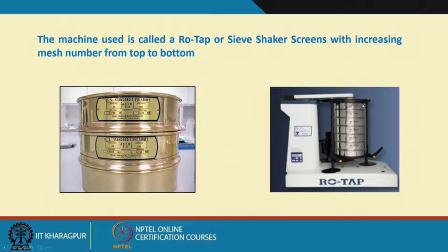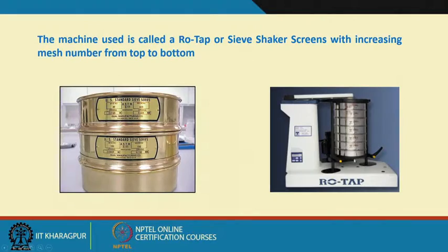So, generally it is a thumb rule that if, for the coarsest sieve, the retained particle weight percent is not more than 5%, then that is the right sieve to start with. Similarly, what will be the bottommost sieve? Suppose my guess is that I have hardly any particle finer than 40 micrometers.